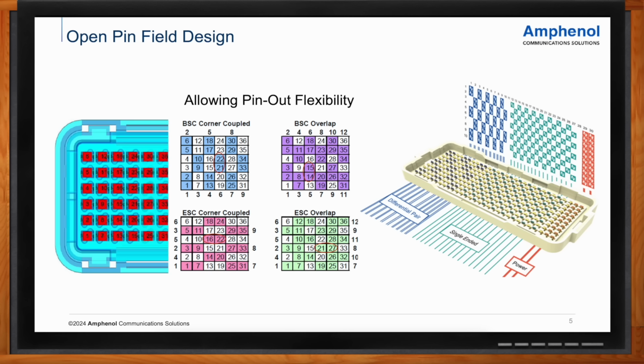And then typically they're also going to run power through these connectors as a very common application. So the trade-off here is with MEGArray, you have an extremely flexible connector. With all the pins being identical, the customer at their PCB level will make a determination whether they want a pin to be high speed, low speed, or power, just in how they lay out their board. And so they've got great flexibility there.